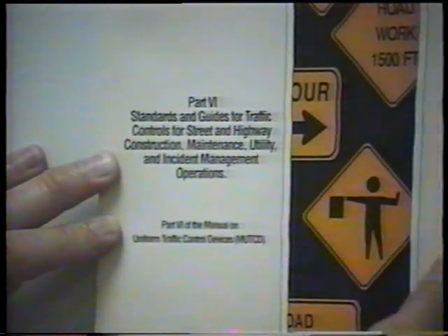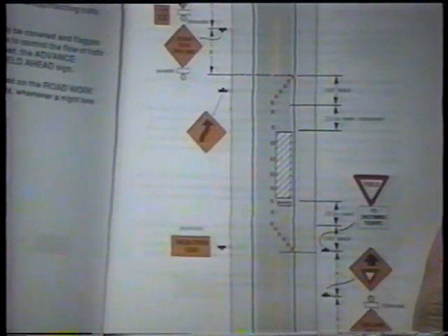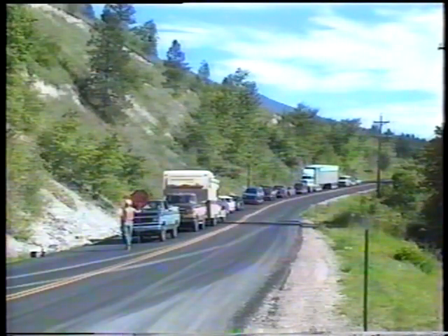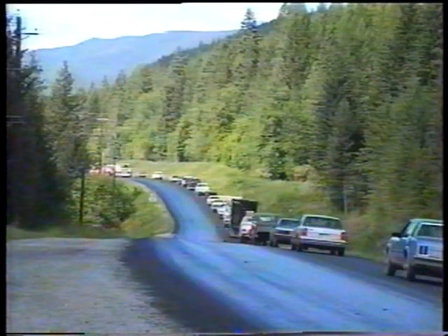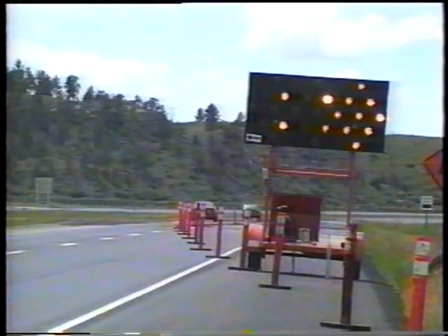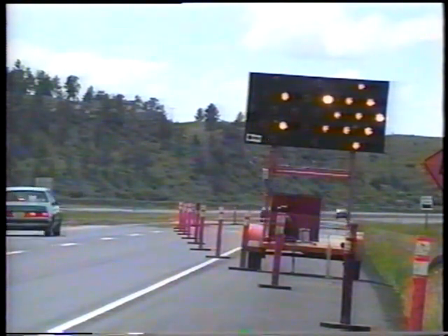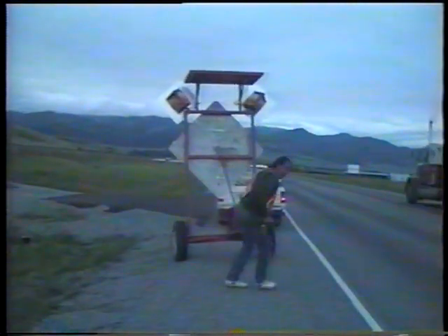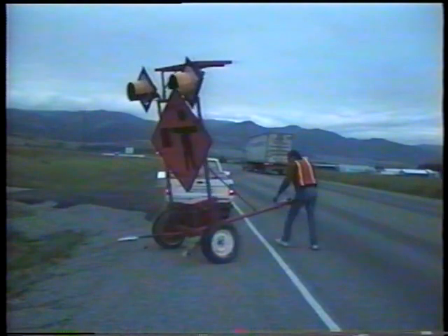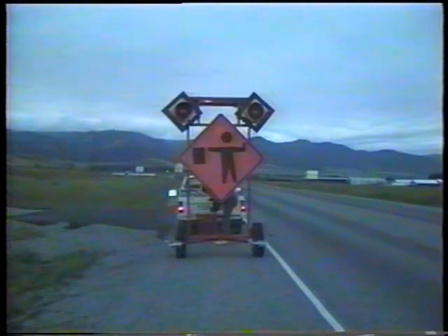First, the traffic control setup should comply with the Manual on Uniform Traffic Control Devices. Second, when traffic has to be alternated through the work area, make sure the flaggers work together to avoid holding traffic too long. Third, report any unsafe conditions to your supervisor as soon as possible. And fourth, make sure all signs are removed or covered when they no longer apply. Motorists learn to ignore signs when they don't see any roadwork.